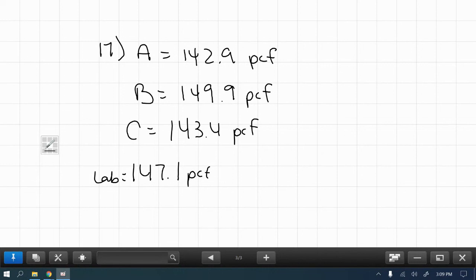these lab tests are already done at the lab. So let's say if we went to Barn Hill, they'd have a lab where they've done some typical densities, and that gives us something to compare it to. Same thing would be for soils, if they're wanting to do density on soils. Most of the time, when they're doing outside densities, they have what they call a nuke gauge. This would have been in soils and foundations, but they actually carried the machine back to Raleigh before I even came on full time. You could set it on there and it would get your density outside of asphalt, sand, whatever, but you have to have something to compare it to from the lab.